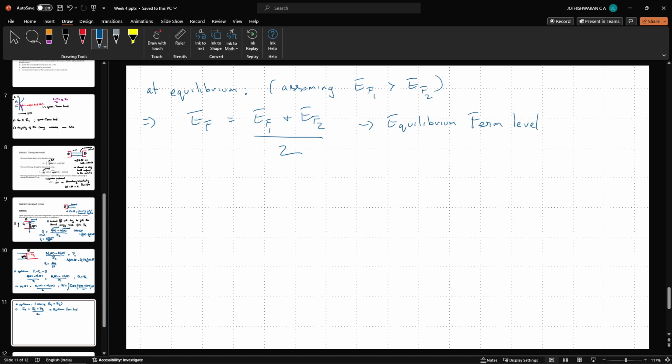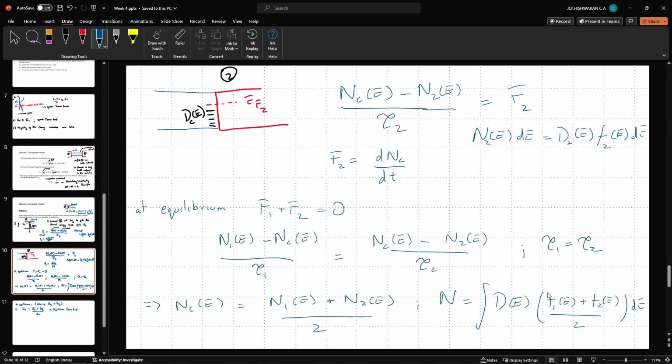Now this will not always be a constant, like the Fermi level will not always be a constant, because we can apply voltages across this channel. So when we apply voltages across this channel, we will have cases where the Fermi level shifts. And again, we are familiar with this effect. However, we are not dealing with that right now, so I am not going to go into any further details about that. So this is the derivation for the stored charge. So this part is done.